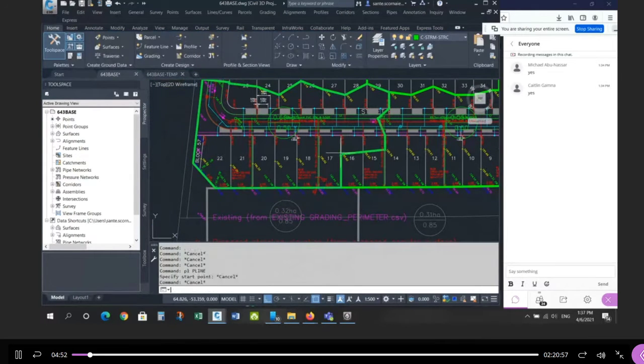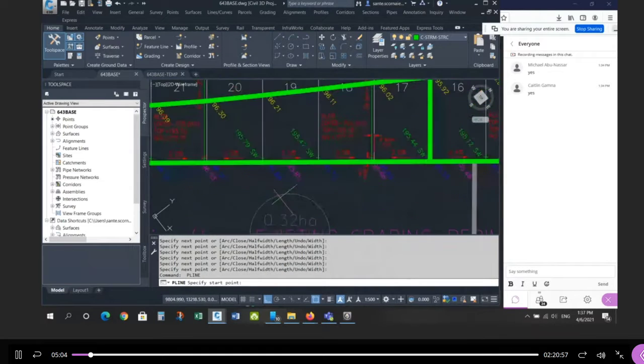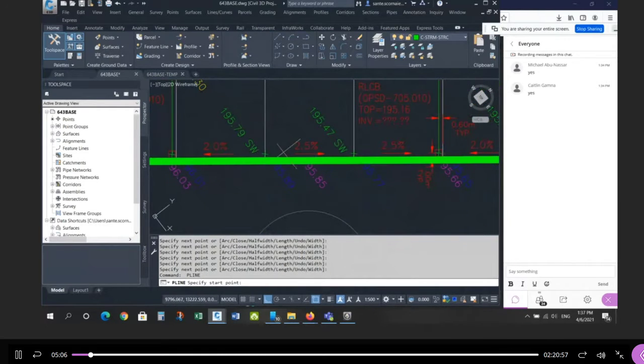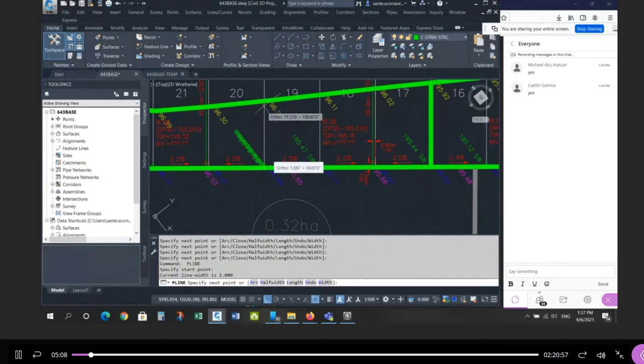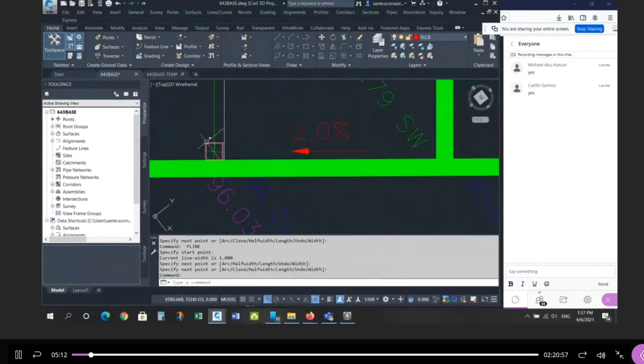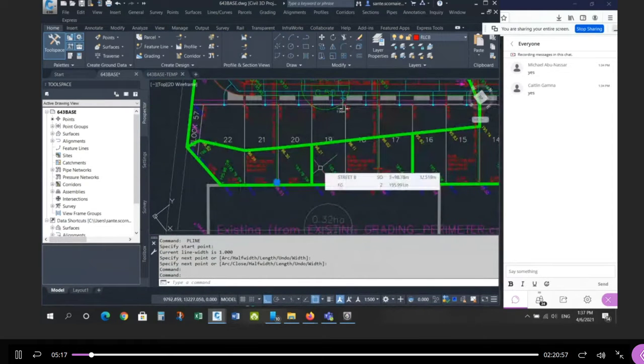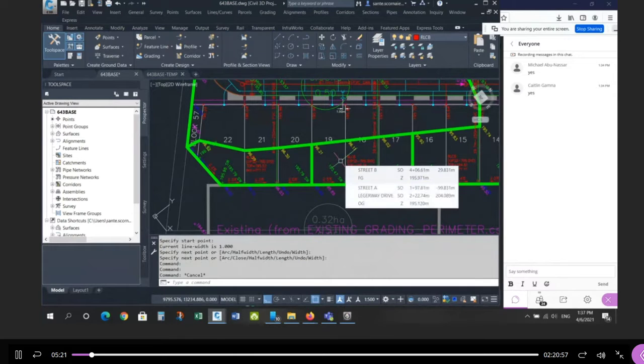And the area to each of those eventually get to this road catch basin. So what used to look like this, what used to be a drainage divide that looked like this, right? Remember, I drew this. These are the split points, and so on. And then in here, you'll see a high point, right? The 2%, 2.5%. So there used to be a split point here. So each catch basin, this catch basin and this catch basin, each had their own drainage area. But because we're not detailing the rear lot catch basin pipes on the design sheet, we're going to combine them.